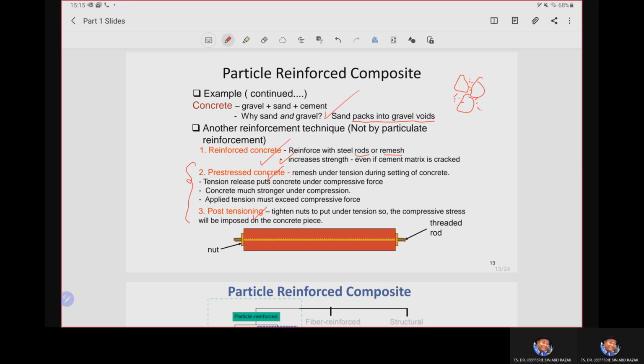We understand that ceramic material, being brittle in nature, is stronger in compression loading in comparison with tension. If we apply tension, the ceramic material, in this context the concrete, easily experiences breakage. So in pre-stressed concrete, the high strength steel wire, we position inside the empty mold and stretch with high tensile force. After the concrete has been placed and allowed to harden, we release the tension, and as the wire contracts, it will put the structure under compression, because the stress is now transmitted to the concrete via the concrete-wire bond.